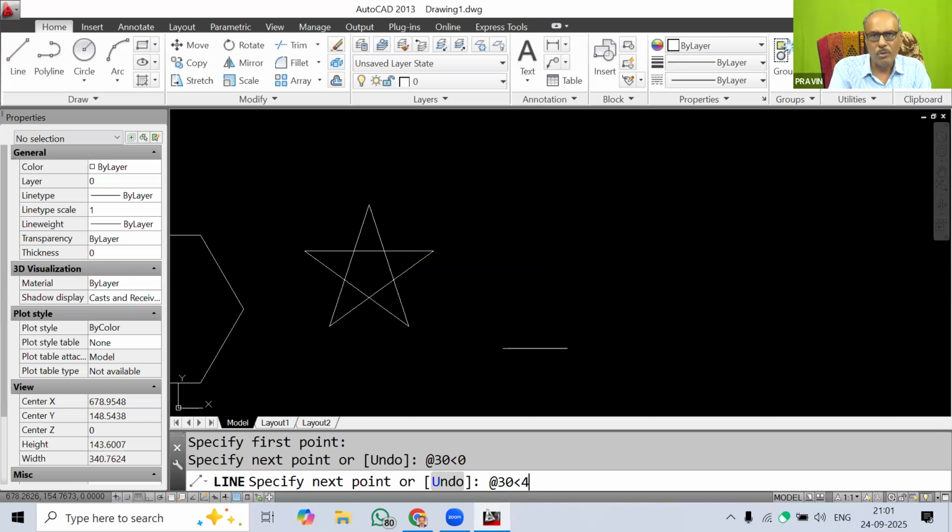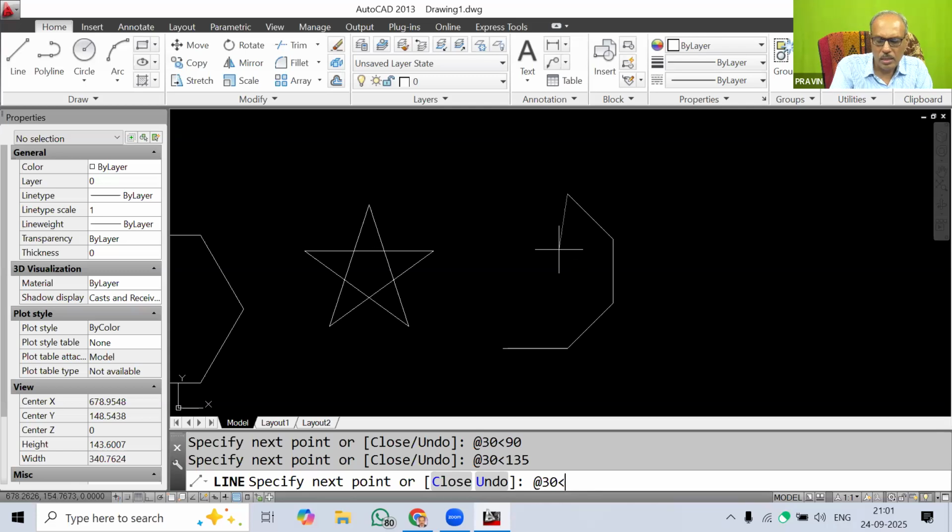So I will take 45 first, then @30<90, then @30<135, @30<180, then @30<, now 180 plus 45 is 225. Sorry, that was a wrong angle. So I will type U so that it gets cancelled. So @30<225.